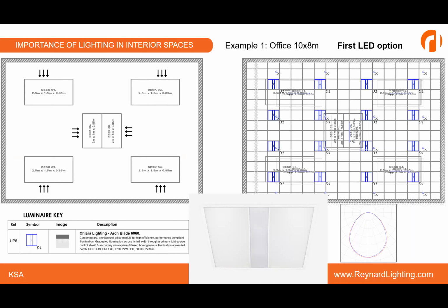Number of 60 by 60 product, but not panel at this time. It's a luminaire where the LED products will be on the top of the luminaire at the center. And you can see the luminous distribution of this one in comparison to the previous one. This is more controlled, and this has more luminous intensity here under the luminaire at gamma 0.